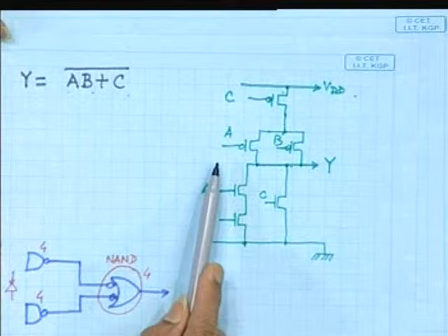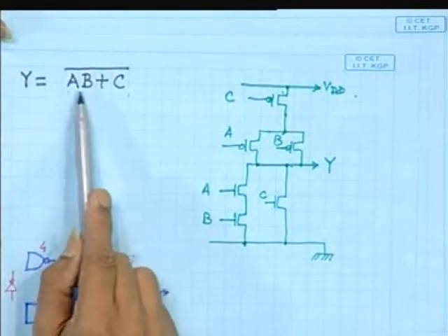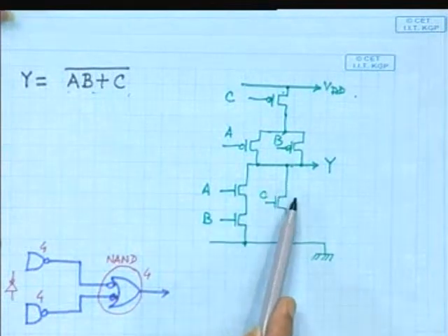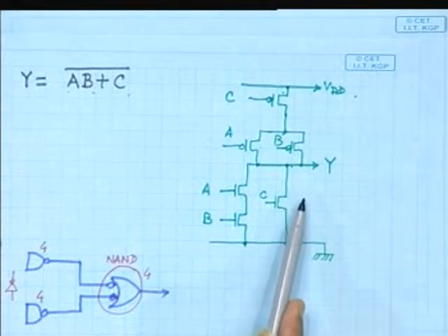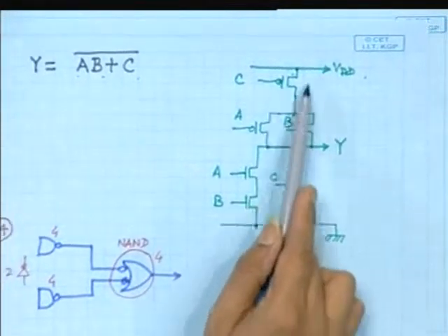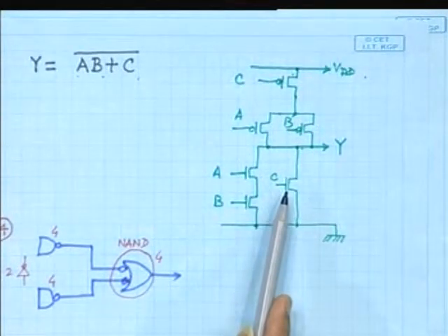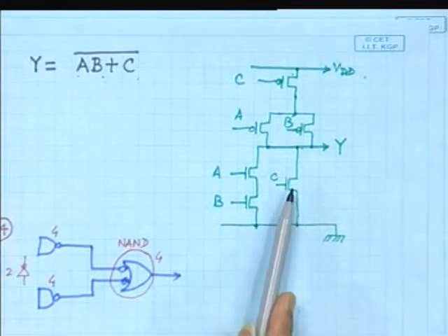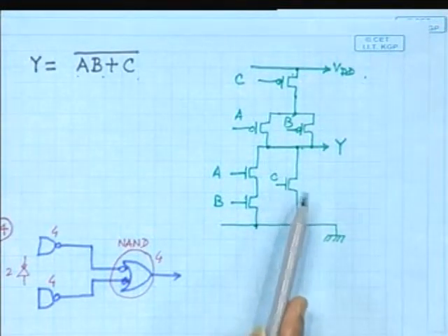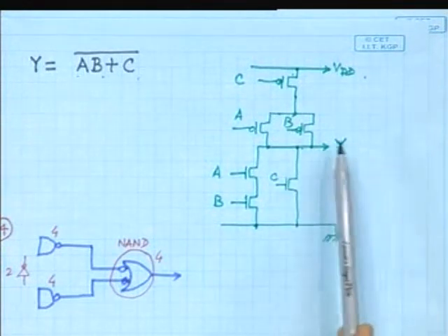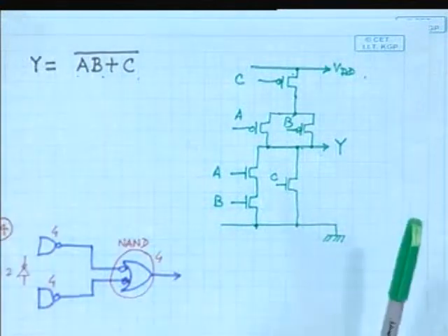You can write a program specifying that if you find an expression like this, this is how to arrange the transistors. But there are many other classes where the topology is different. First of all, you have to choose which topology you will actually use. There are several factors, starting from speed, power and area. So we are going to discuss that.